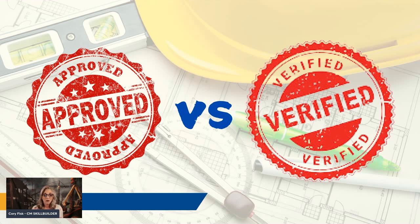So if there's 8 hours of labor and 8 hours of backhoe and form work that was included as part of the materials, then we're verifying that the contractor did, in fact, invest 8 hours of labor, 8 hours of a backhoe, and the materials for form work. However, it does not mean that we're approving that we also agree with the contractor that that scope of work is outside of the original contract.